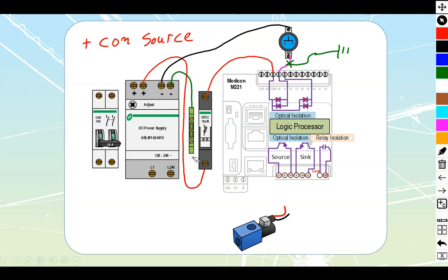Because in a lot of industrial applications, we're going to have multiple DC supplies. You might not have grounded your DC supply, but if it shares a common with other DC supplies, one of which is grounded, there will be a path back through. I am very, very leery of using a sourcing type of input for that fact.